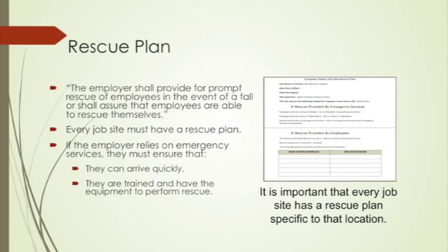Rescue plans are an important part of building a safe job site. Ensure that every job site has a rescue plan specific to that location. The employer shall provide for prompt rescue of employees in the event of a fall, or shall assure that the employees are able to rescue themselves. If the employer relies on emergency services, they must ensure that they can arrive quickly and that they are trained and have the equipment to perform rescue. A sample rescue plan is included in the forms folder of the resource CD.